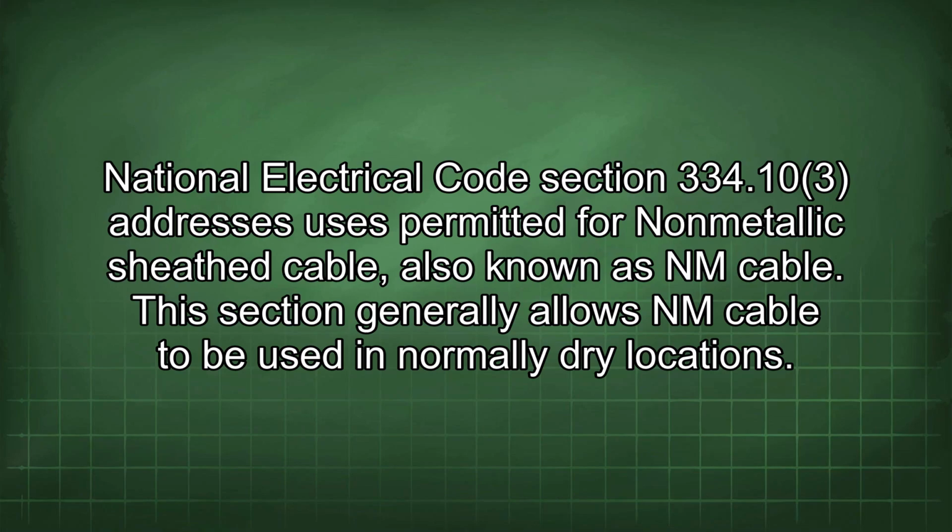National Electrical Code Section 334.10.3 addresses uses permitted for non-metallic sheathed cable, also known as NM cable. This section generally allows NM cable to be used in normally dry locations.